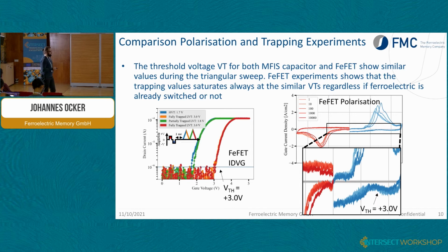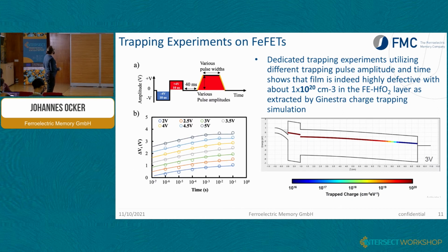This was what Sven was talking about before, so you have to wait like a second or something like that, and then these traps also come out. So there are traps that are already released during the down sweep, and for the traps that are deeper into the stack, you have to wait a little bit longer.